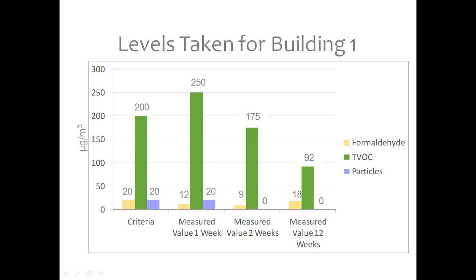That's how you measure emissions of chemicals coming off of products. We're used to seeing grams per liter, or g/L. That's content of chemicals. Micrograms per cubic meter is emissions of chemicals. So the requirement was that it meet a 200, and we're looking at the green bar, which is the total of all VOCs in that particular building.